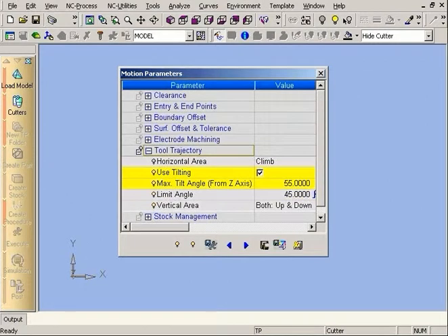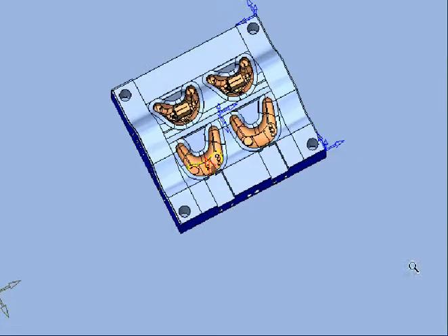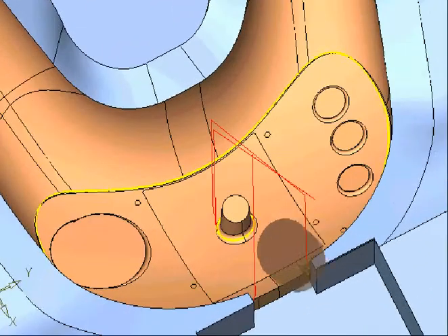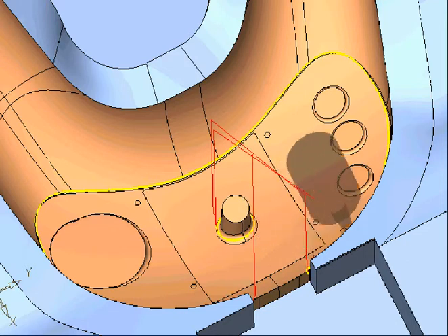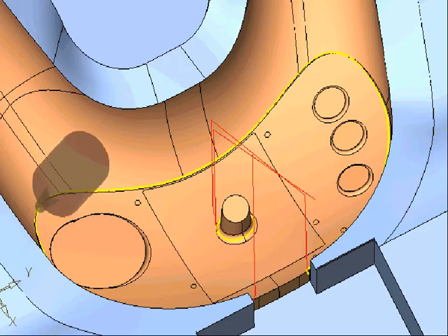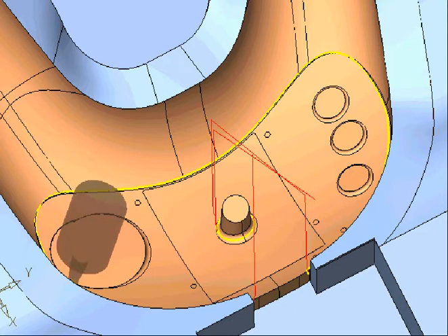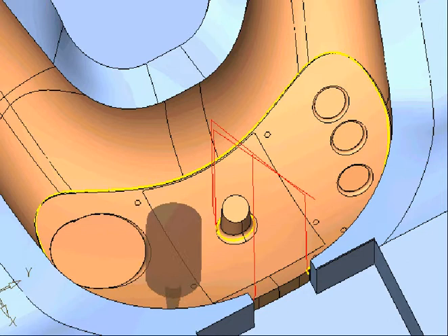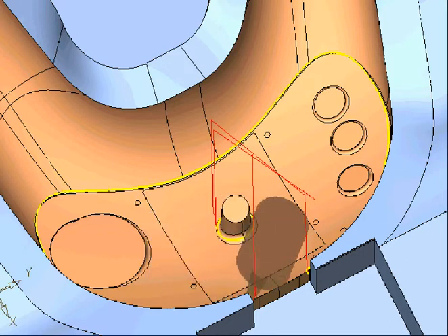Here, automatic 5-axis tilting uses small, short tools with conic shank and large holders to machine deep cavities with small details and small corner radii, enabling milling instead of electrodes. 5-axis positioning reduces the number of setups in the process. This is supported by 5-axis material removal simulation and 5-axis machine simulation, a real-life machine environment with full gouge detection. The application also includes 5-axis trimming of edges for vacuum-forming products.